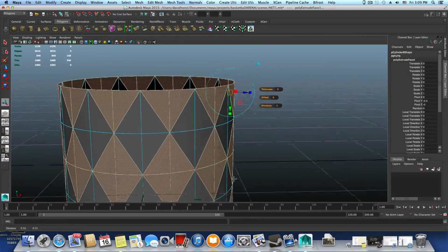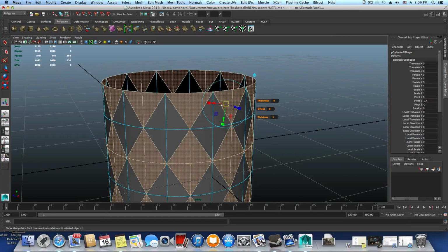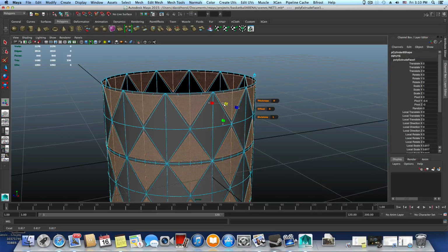And after you extrude this, you're gonna click on one of those. See, each handle arrow has this cube on it, but in the middle here we don't have a cube. This is just a yellow square. So if you tap on one of them, just click with your left mouse button and release. Just fast, click and release. You will get this middle one, and then you can grab it and extrude it just a little bit that way. Okay.